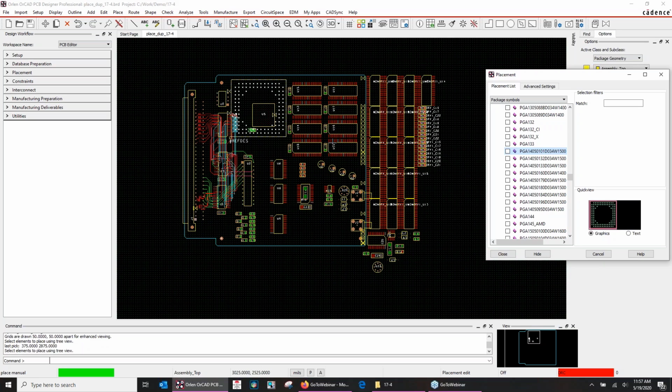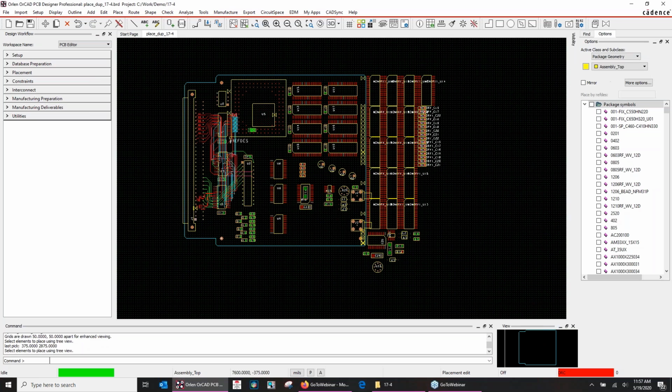Now when they do the schematic for real and I bring that in, all I have to do is assign those parts, a lot like what I was doing down here when I was assigning these parts out here to the parts here. I don't lose the work I did on the what if, and the engineer didn't waste a lot of time doing that work on the schematic, and then she gives me that net list, only to find out that I can't get these parts on, we have to do something else. Maybe put DIMM connectors in there and add DIMM boards if we've got the room. But understand that you can do a what if, and you can plan ahead. It can save a lot of work that way.